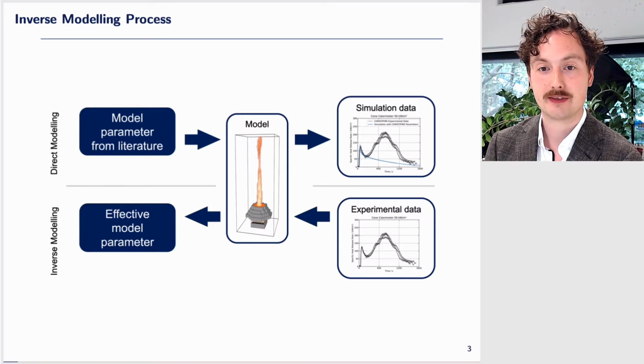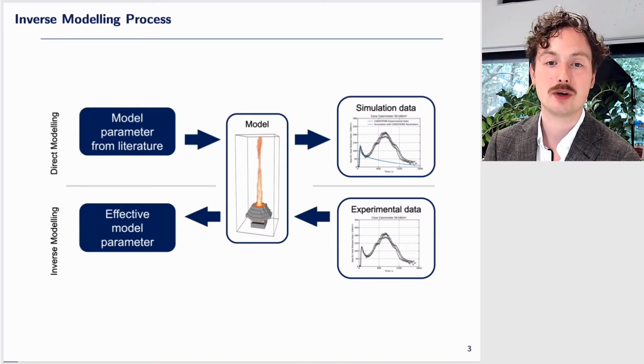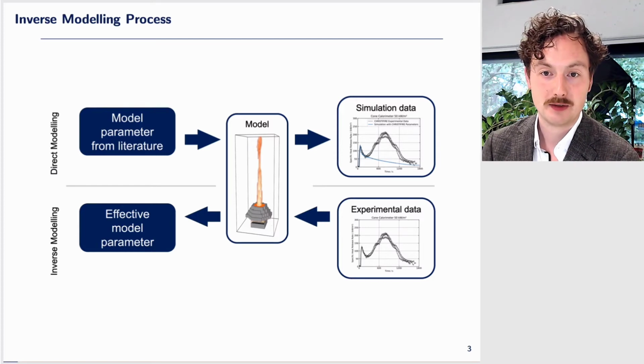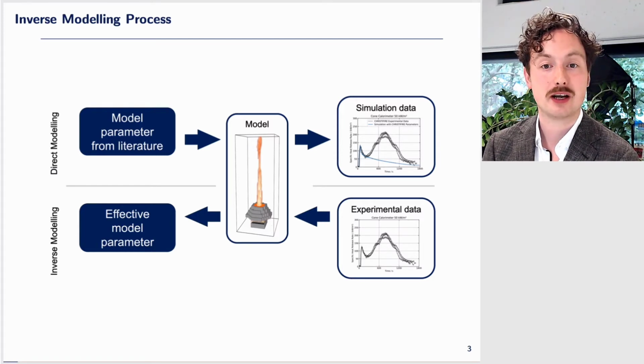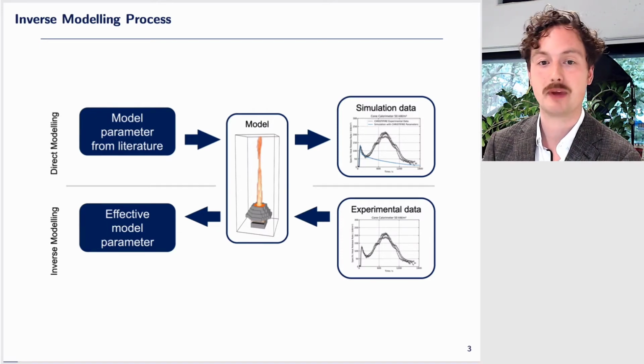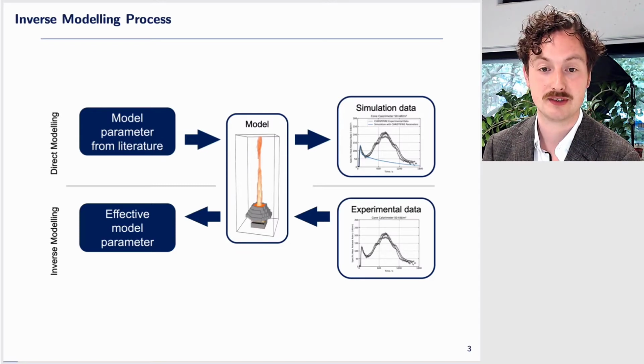That is, in fact, the situation we have to deal with when we want to model pyrolysis. Please note, the obtained parameters are so-called effective model parameters and do not necessarily represent any real physical or chemical parameters of the virgin unburned material, and certainly not any of the intermediate materials that may be formed during the sample decomposition.